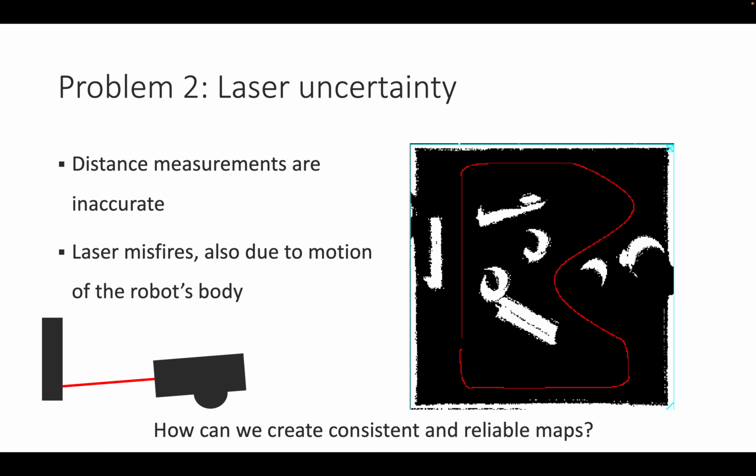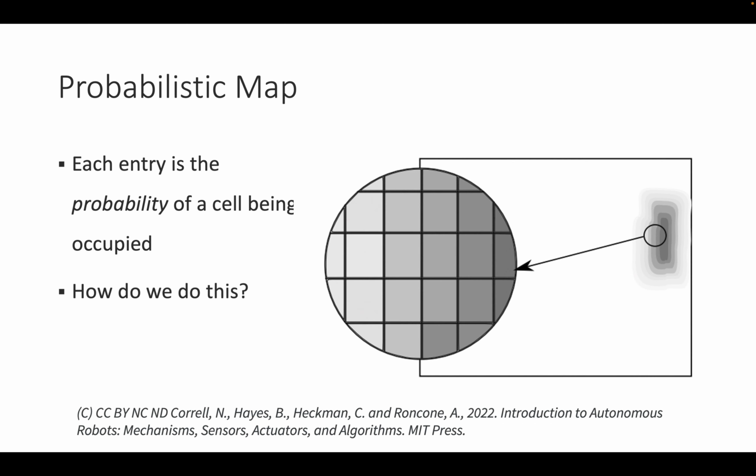So how can we deal with this? When you think about it a little, the idea would be you have to see something multiple times for it to be really an obstacle, and we can do this by just counting the incidences of an obstacle happening at a certain grid cell and derive some notion of probability from that.